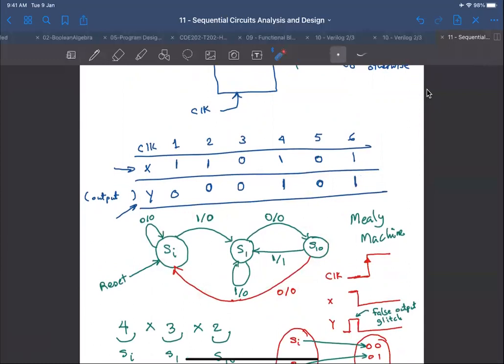So basically what you should do is to follow the path in which the circuit will detect the sequence. So you start with SI, the initial state, and then get a 1, output is 0, and then a 0 where the output is 0, and then a 1 where the output is 1. You have to figure out to which state you go next. This depends whether the overlapping is allowed or not. If overlapping is allowed, then you can use whatever part from the previous sequence to be part of your new detected sequence.